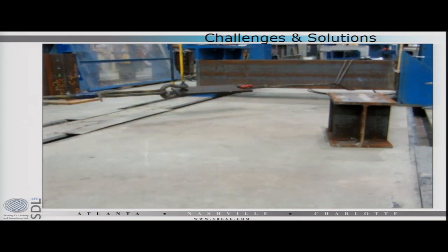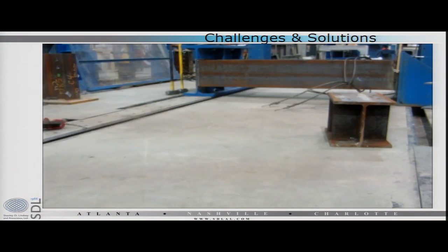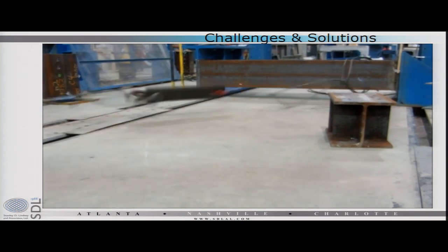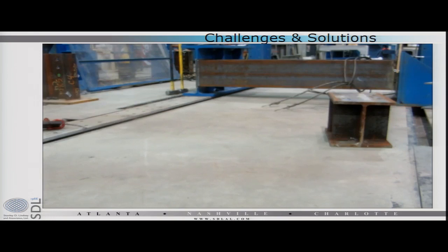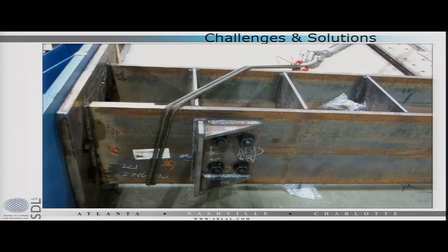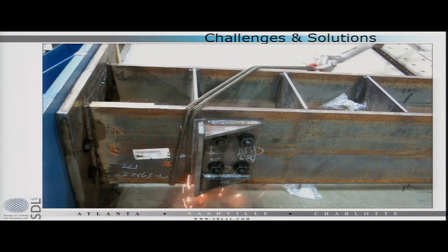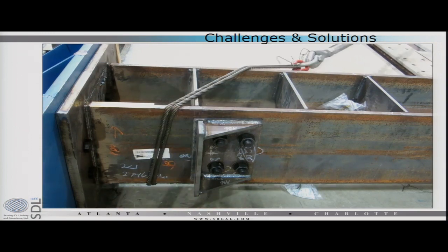We did manage to break a couple of the shackles and one of the turnbuckles too. So again, no slip. These were at fairly low angles, no slip. This one was at a fairly high angle. Slip. That's what we're trying to prevent.